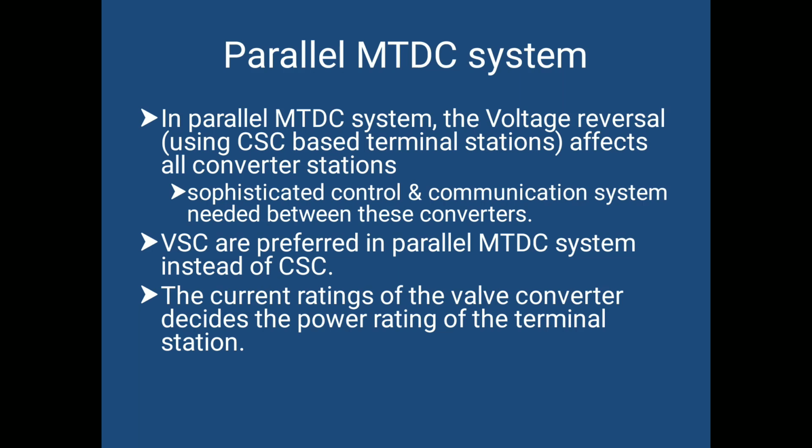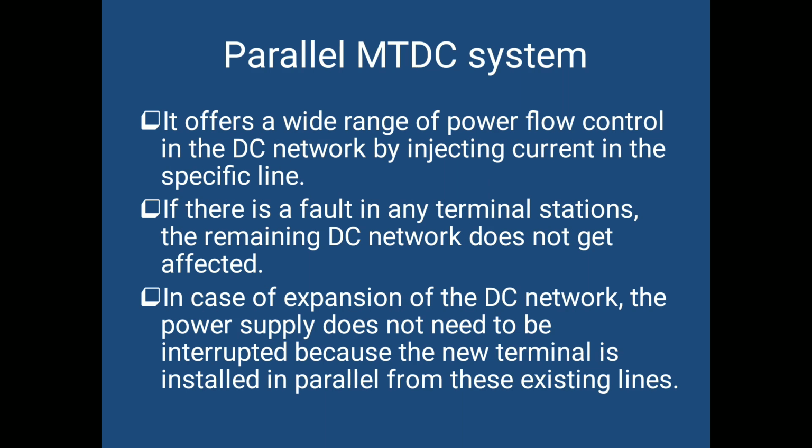And since the voltage remains constant in the VSC MTDC systems, the current ratings of the valve converter decide the power rating of the terminal station. It offers a wide range of power flow control in the DC network by injecting current in the specified line.